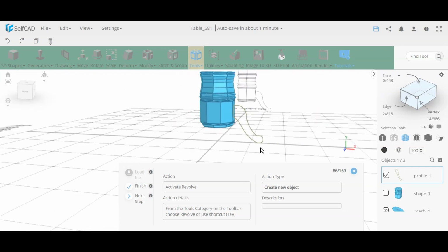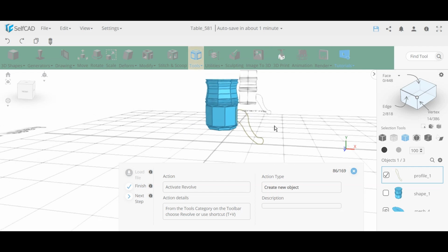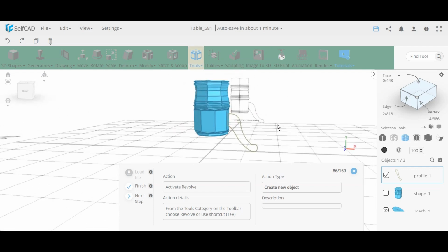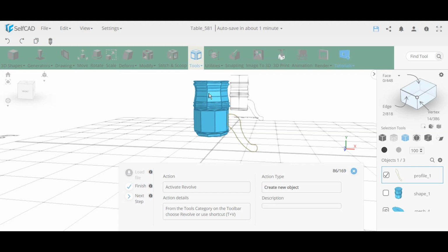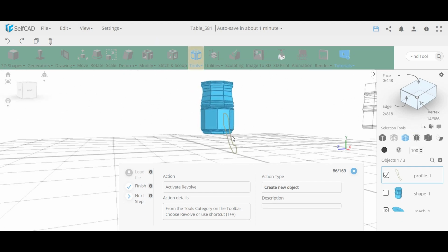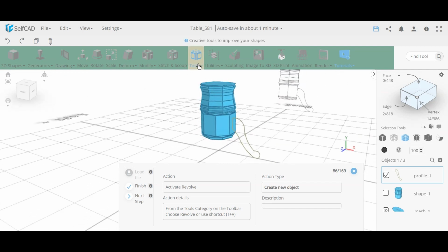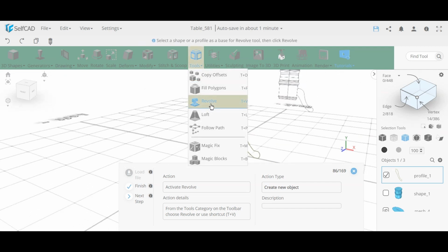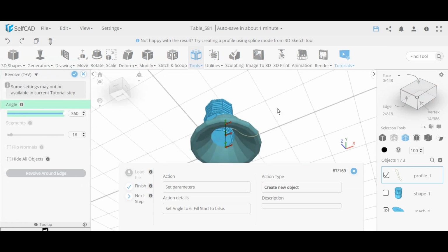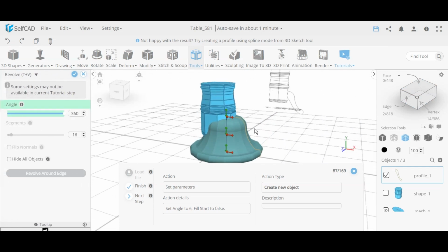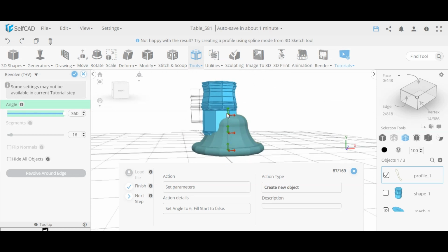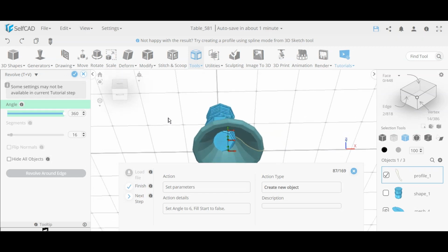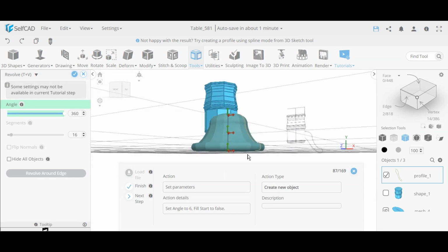And as I said in the beginning of the video, everything here is a cylindrical type of thing. So initially we started with a basic cylinder, then we used a custom base cylinder we call shape generator, and now we have a very custom drawing, but we're going to do the same thing, a rotation type of shape, which is called revolve. Now if you revolve this, it revolves around an axis. The default axis is what's shown over here, and if you revolve around it, you can see it traces this shape around, revolved.